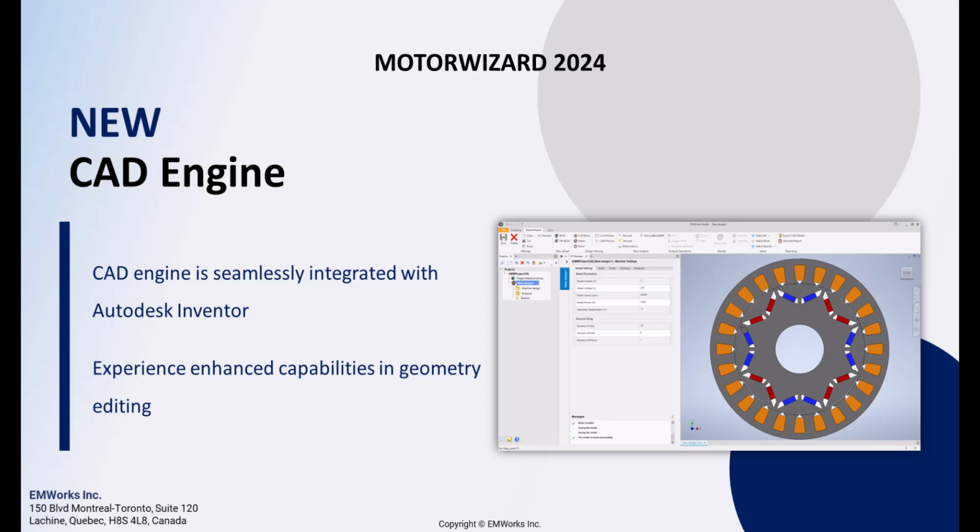You can take advantage of Inventor's industry-leading parametric modeling tools to precisely manipulate and edit the geometry of your motor designs. This includes the ability to push or pull faces, to extend features, add holes of various shapes and size, apply fillets, create additional cuts, and so much more.